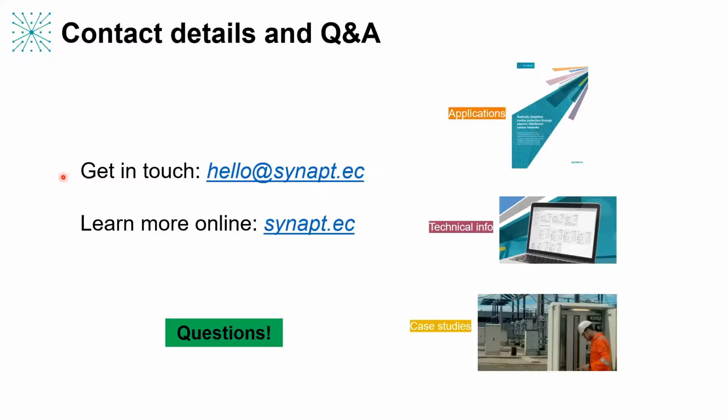Now, that's actually prompted some other questions. Let me jump to that one, Neil, which is: if you zoom out from this, you're giving some examples here about a feeder which has got several branches, and the fault could be contained in different branches. So you've got overlap and underreach problems. We get that, that's been explained. The question then that was prompted is, how do you take that into other domains where you haven't necessarily got multiple feeders, but you maybe have a very long feeder which requires breakdown into multiple zones? So you've got this sense of multipoint.